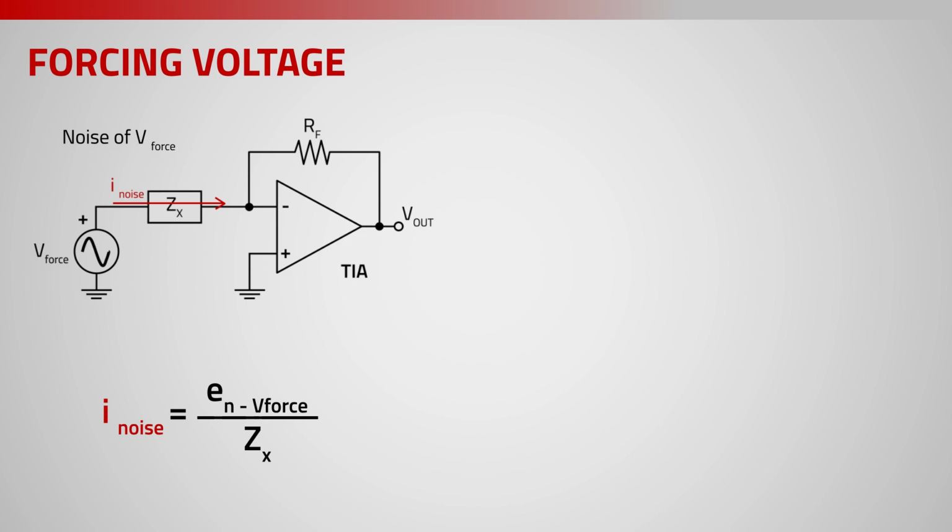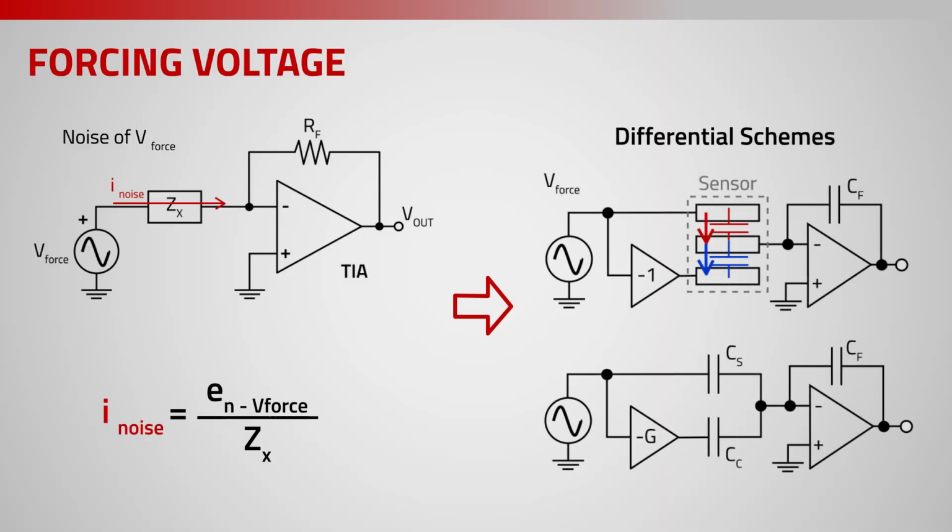In the case of impedance, we have a couple of additional noise sources that have to be taken into account. First of all, the noise of the signal generator, which excites our unknown impedance. This will produce a current noise that gets into the chain. In order to reduce this effect, we can adopt a differential readout scheme. In particular, this is suitable in the case when we can fabricate very well matched devices, or we can use some kind of active tuning in this type of calibration.